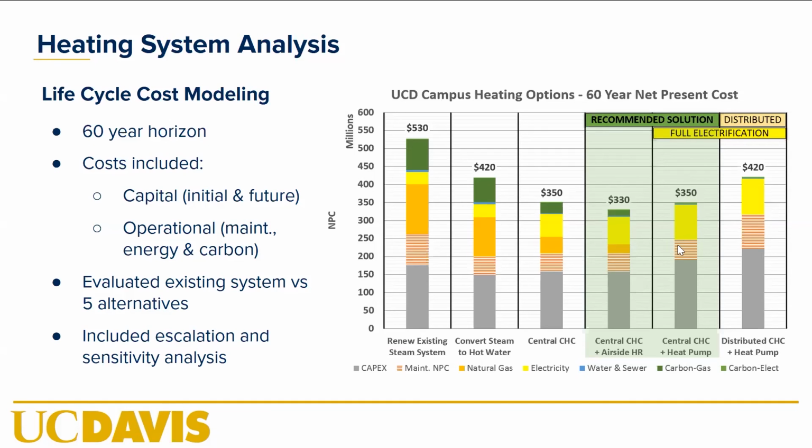So the full electrification that still is feasible is in the winter months when we don't have the potential to do the heating with the heat recovery. We can run that chill water when we can't get the heat out of the buildings with the chill water. We can run that chill water into the ground and do geo exchange and pull it out at a warm enough temperature then to run our heat recovery chillers and make the heat out of that, or run it through air source heat pumps and pull heat out of the air. Either way, it's a little bit of an electrical load.